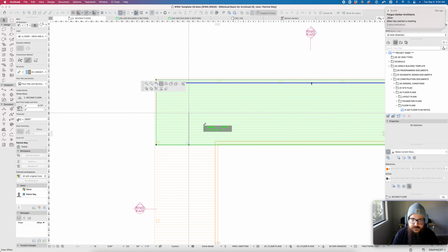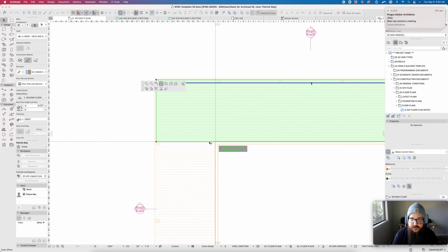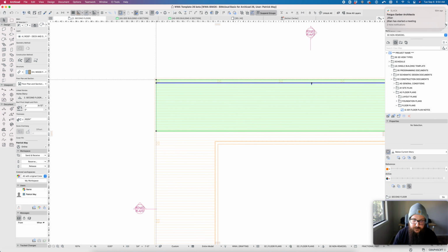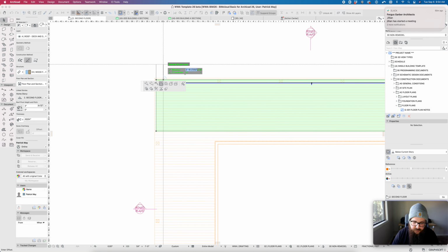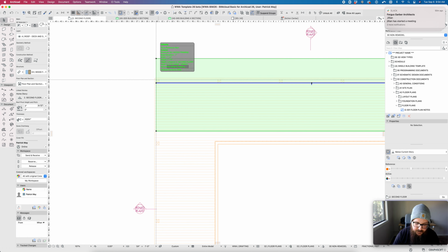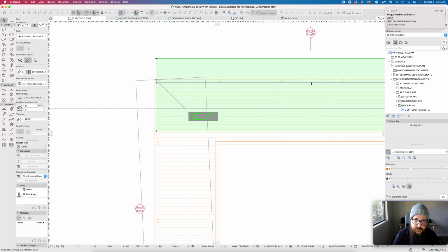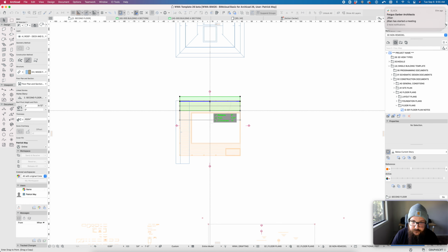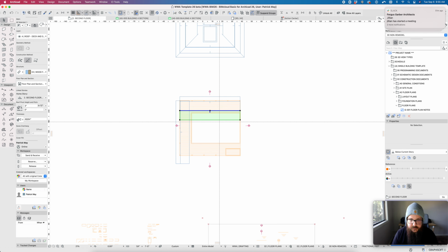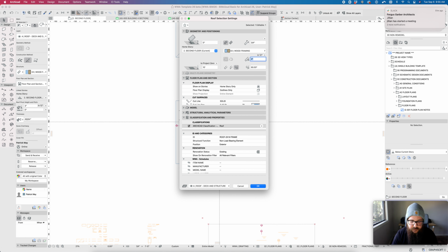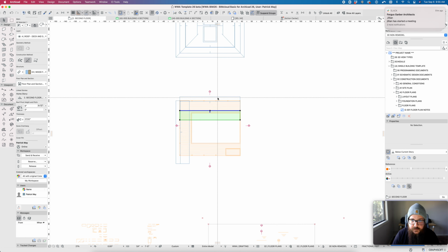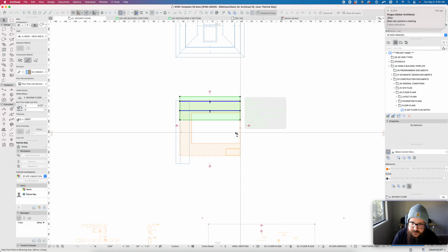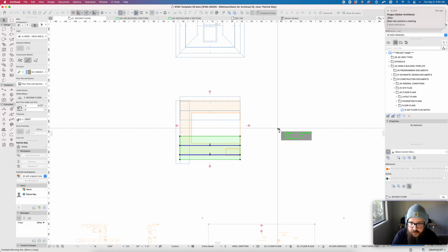Now, what you can do is be really precise with this. So this is one of the advantages over the multi-plane roof, is that you can say that this pitch break happens 2 feet in from here. I can pull this roof overhang out 4 feet, for example. I can mirror this across this corner, Command Option M, and start sculpting this out. I can then set this roof, if I pull this over to here, so that pivot line is going to happen right where the top of this roof is, and I can say that this is a 6 and 12 slope. And let's go ahead and mirror a copy of this. This little tick mark indicates the center of that wall.